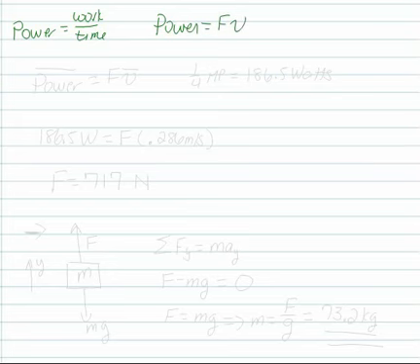And remember, this could be an average power or an instantaneous power. To make it average, we can put bars over the word power and over V. So how do we know which one to use? Once we know we have a power problem, the question usually is going to deal at some point with a velocity if we're going to use the power as FV. So if you are given a velocity or the question is looking for a velocity, use the power as FV.